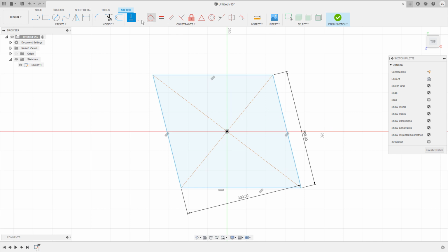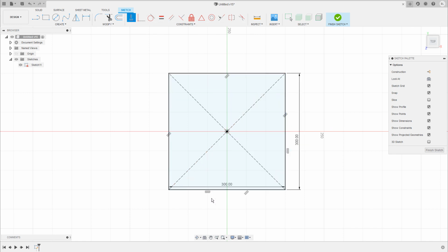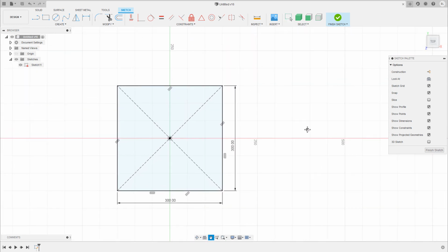And then the tool is still active also on this line. So I have assigned a horizontal and a vertical constraint to the drawing. And then I've turned it into a fully defined sketch again. So in this case, and because we have also added a vertical constraint, it was not necessary to add an additional perpendicular constraint to the corner. You don't have to anchor a sketch to the origin to turn it into a fully defined sketch.